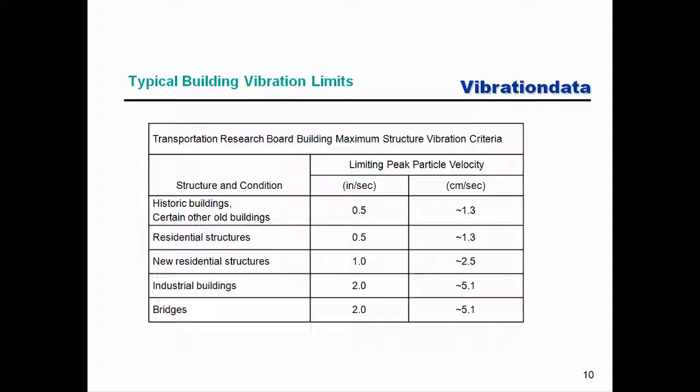Okay, here's some typical building vibration limits. So for example, if you had a charge mode piezoelectric accelerometer, you could mount it on the floor of a historic building, and then you could take that signal through the Brüel & Kjær 2635 charge amplifier and get the velocity output. Or if you just have an acceleration time history measured via a different measurement system, there's different post-processing digital integration that you could do as well. We'll be covering that here shortly.